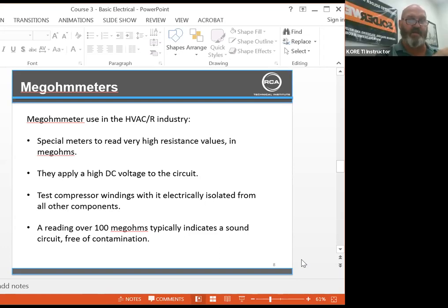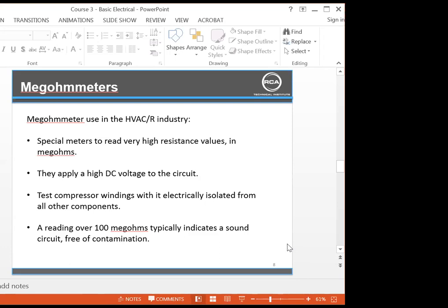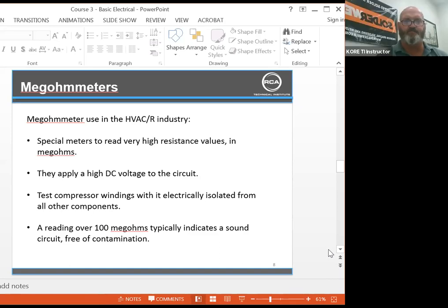Awesome. So then the megger really sounds like it saved some diagnostics and gave you a better troubleshooting call. Oh, absolutely. Because I couldn't tell the integrity of the windings with a regular meter and just regular ohming it out. It was under load. And after they had been working for a while and started heating up is when it was tripping. Awesome. Thanks, man. Appreciate it. Yep, no worries.